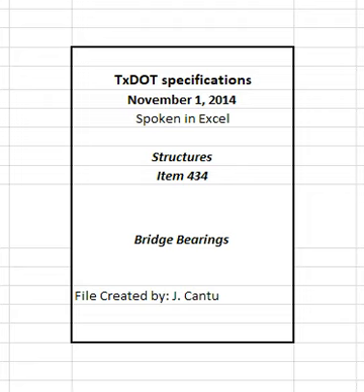2.3.3.5 Coatings. Provide coating materials as required in accordance with item 445, galvanizing, or DMS 8104, paint, shop application for steel bridge members, unless indicated otherwise on the plans. Submit fabricator preferred alternative coatings to the engineer for review and approval.